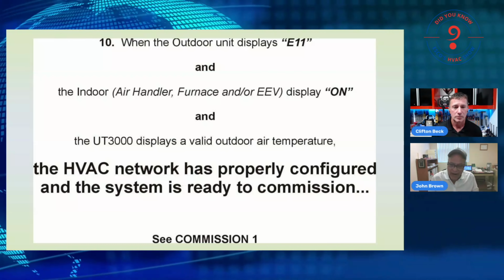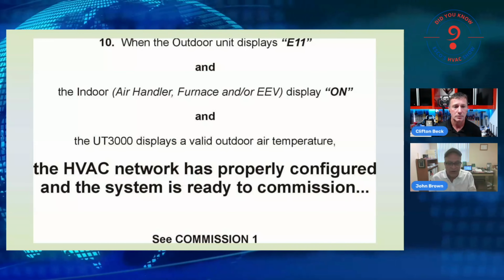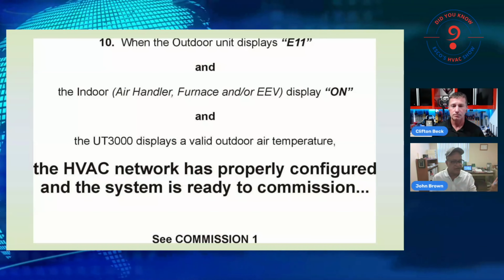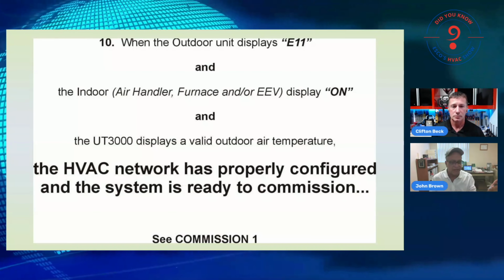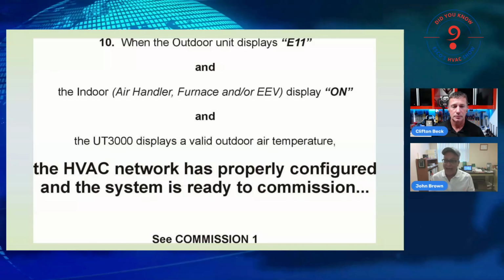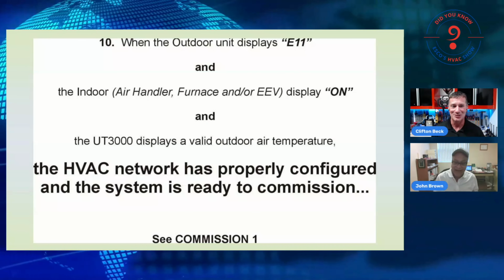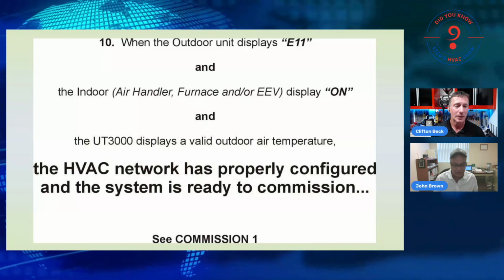The indoor air handler, the furnace circuit board displays on. E77 is no longer displayed on the EEV circuit board. And the UT-3000 now shows and displays a valid outdoor air temperature.